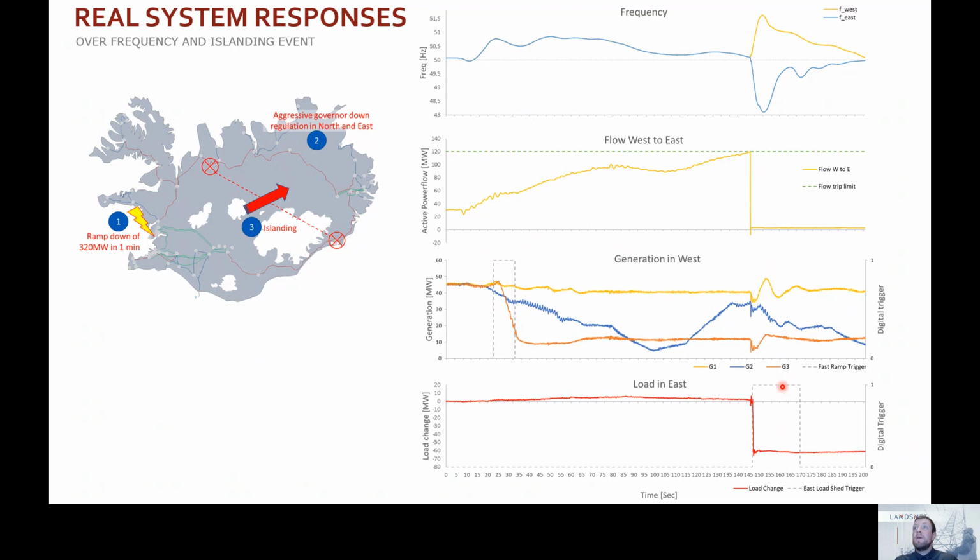Despite that response, if we focus on what would have happened if we had more resources within the wide area control domain, for example, these two other generators within that same plant with the same control, we had about 50 megawatts still left of regulating power if we would have the same response in that plant. And that 50 megawatts would clearly drop the overloading from the western part to the eastern, and we would have avoided this huge event which tripped lots of customers in the end, and tripped even units in the eastern part. So we had the opportunity to minimize the frequency drop a lot.